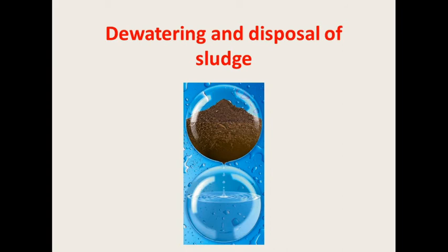It needs electrical energy and may require a flocculant aid like a coagulant. It can operate continuously, and mechanical thickening equipment options include screw, drum, belt, and centrifuge. So these various types of equipment, that is belt press, drum press, screw press, or centrifuge, can be used for mechanical thickening. This technical system requires a high degree of operator supervision and training, meaning skilled supervision is needed for mechanical thickening of sludge.